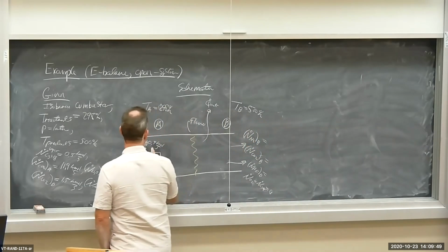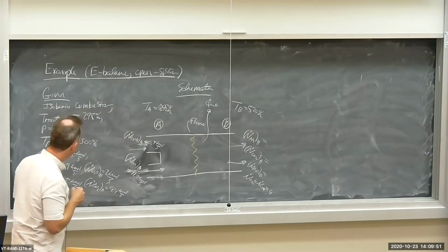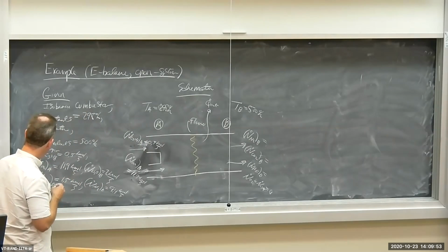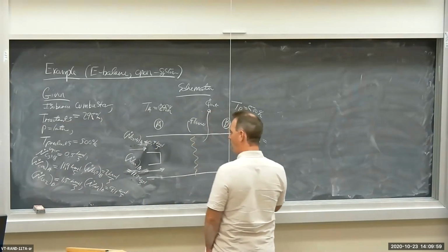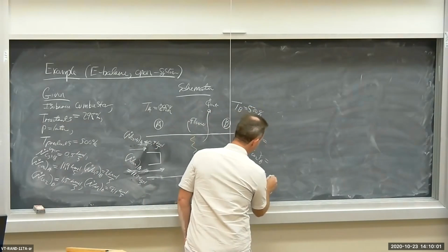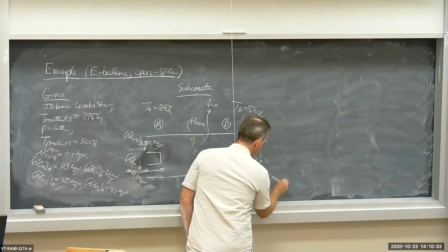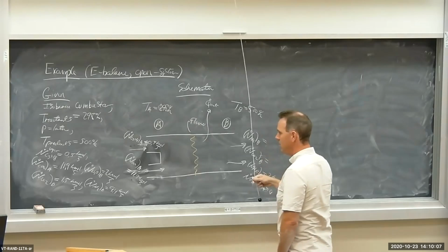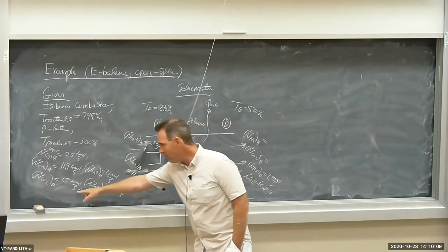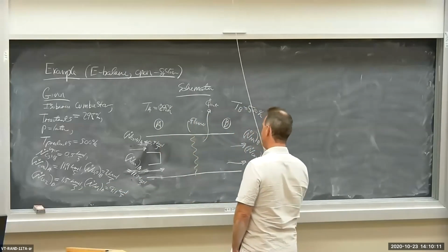With 0.5 kilomoles per second of propane being burned with just enough stoichiometric air, the mole flow rate for the H2O, the water vapor, is going to be 2 kilomoles per second. The mole flow rate for the CO2 is going to be 1.5 kilomoles per second.